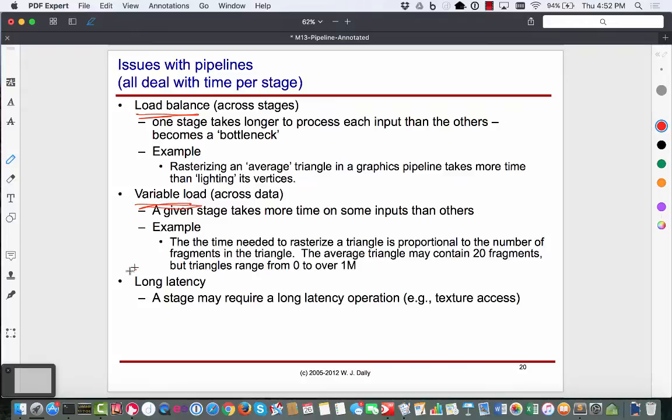And then finally, longer latency. We did see that the latency did go up because of the register delays and all. So while it doesn't go up by a factor of n, it does go up because of that added factor. So there is an impact on latency which one needs to worry about also. So pipelining comes with challenges, makes the whole design process tedious, but is oftentimes worth it.